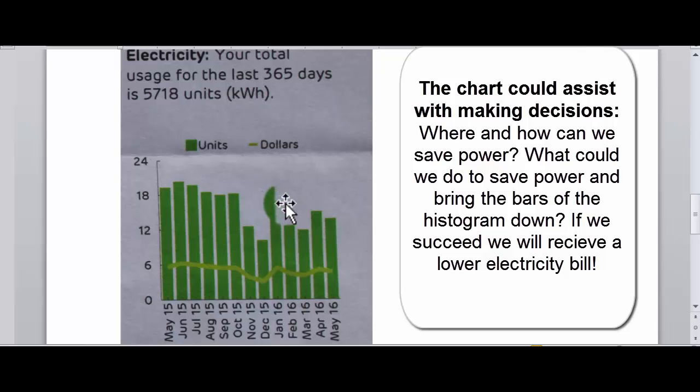Now we could make a decision here, because the people use a spa pool, we could use a solar thermal panel. That's the system where the pipes are filled with water, the sun heats it up, and that water gets sent to the hot water cylinder, but it could also be sent to the spa pool. So a saving is possible by just planning and installing different systems.